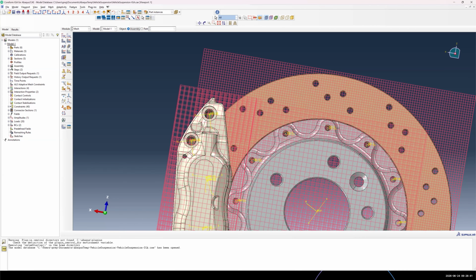Okay, great, thank you. Another question: how do the IGA results compare with a TET mesh? Why would I prefer IGA to a TET mesh? So the answer is both TET meshes and IGA are Galerkin methods. And so they follow the exact same theory as far as mesh convergence as you get from Galerkin theory. So in principle, as you refine both a TET mesh and an IGA mesh, you should get the same answer.